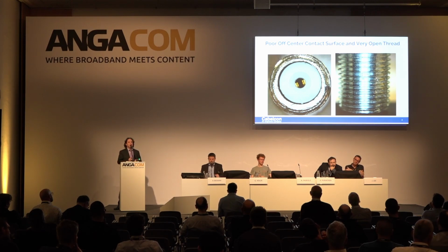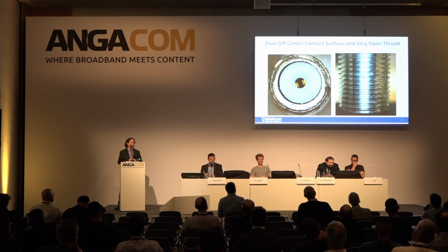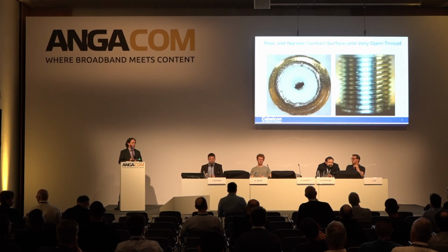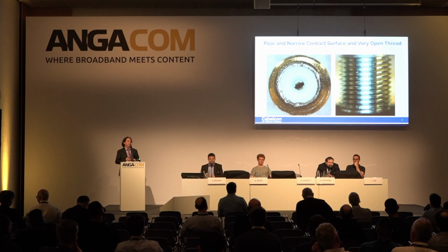And also the shape of the threads can have a big bearing on what's seen, and how well the connector or interface that you're adding to this would work. In this case, these are very thin U-shaped threads on the port, which could lead to poor connection between the threads on the nut. And other things we've seen with that front face, you can get very narrow pieces, where the surface area that's available to connect to the F port being added, or the F male connector, is small, and again, variations in the thread.